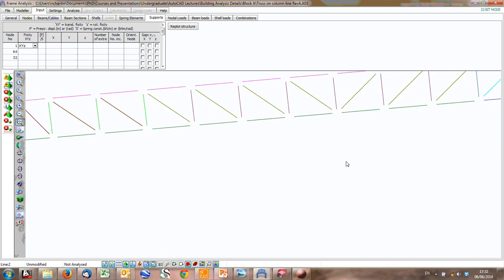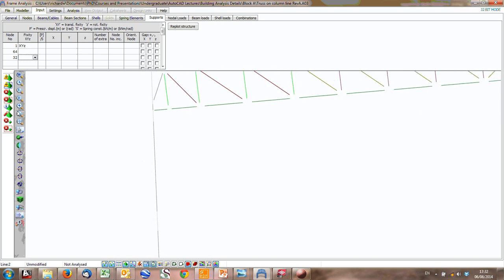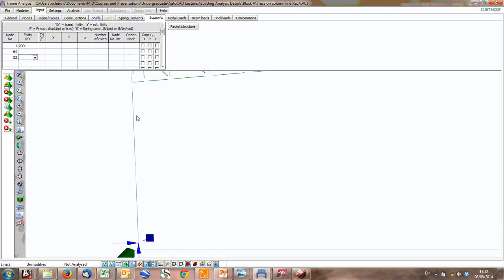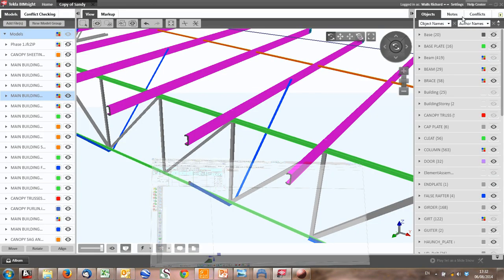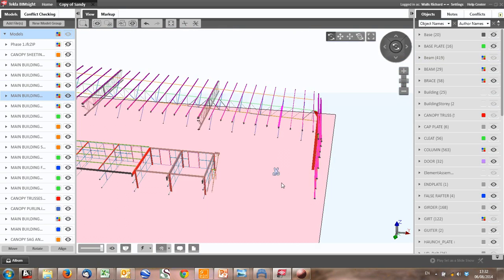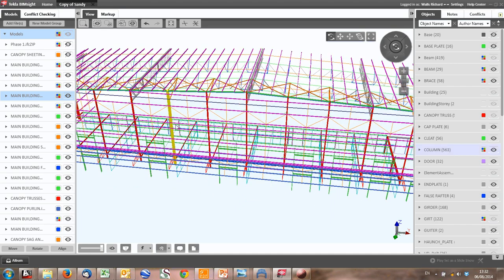And the same thing with the column. You might think the effective length of this column is from there to there, or from there to there. But just see what prevents it buckling sideways. And that's where either you've got the girts or your knee braces. So it depends also if it's the inner flange or the outer flange. So all these things you have to consider when doing a design and carefully take your loads through.